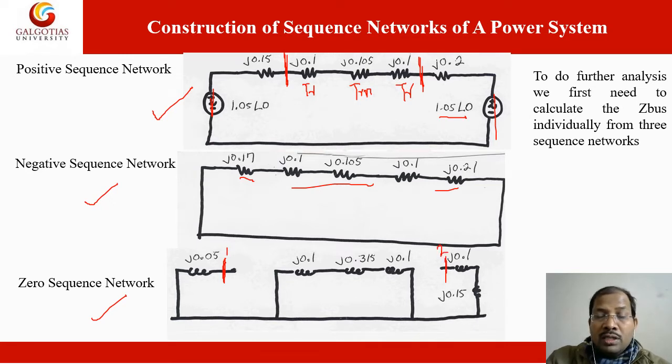For the zero sequence of the generator, there is Zn equal to 0, only Z0 will be there, so you have to connect from bus 1, and here the Zn is 3 times Zn. So for the machine, the Z0 they have given is the Zy, and 3 times Zn you have to write.